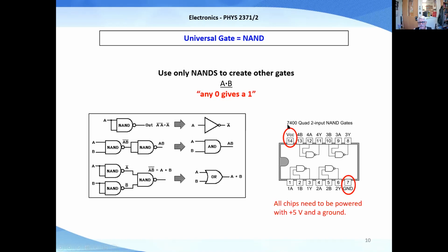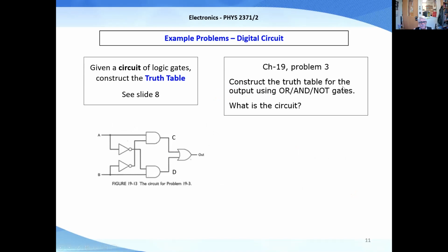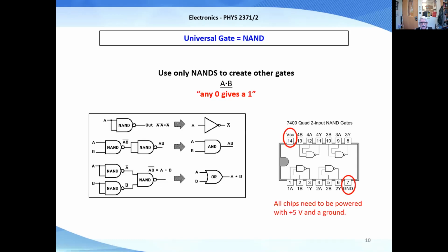And the NAND gate is a 7400. So the 2 zeros say that it's a NAND gate. They also have 7402, 7404, 7408, 7432, and so on. Any questions on that so far? So we'll get into this a little bit more on actually using these.